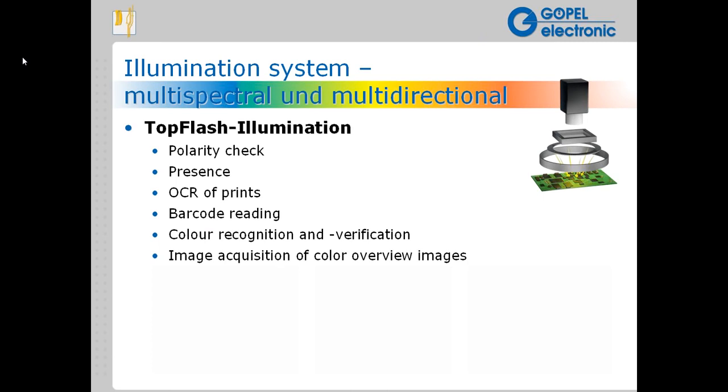We have some capabilities such as an infrared metaflash illumination. Our illumination capabilities really are full spectrum from infrared to UV. So we can produce an infrared capability that helps in many different cases of challenges with contrast. In this particular optical image on the left, as you can see, those SOT packages are almost invisible. However, when you look at them in the infrared spectrum, they become very visible. The markings are visible, the bodies are visible. The overall contrast is greatly improved, and the understanding of the makeup of the board is greatly enhanced.